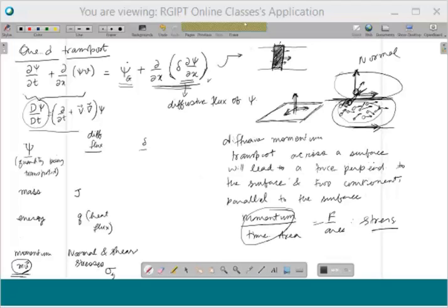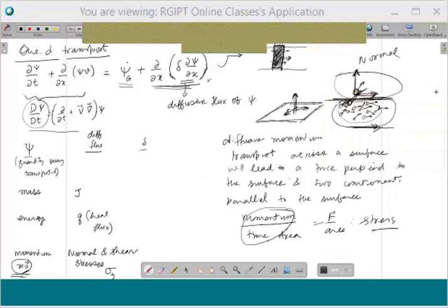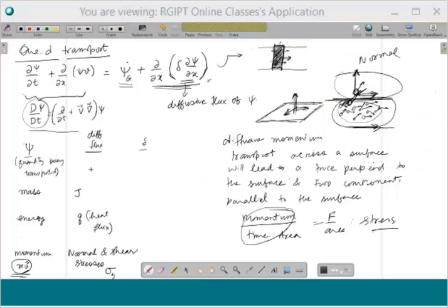So now, all right, let's proceed then. These would be the fluxes. If you consider different quantities as mass, momentum, and energy, the corresponding fluxes which we identify are given by this quantity. These are the diffusive fluxes for different types of transport: mass flux, and if you think of this as energy transport, there is heat flux, and momentum transport corresponds to momentum flux, which is nothing but stresses, right?